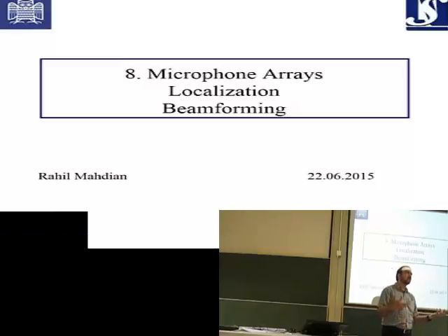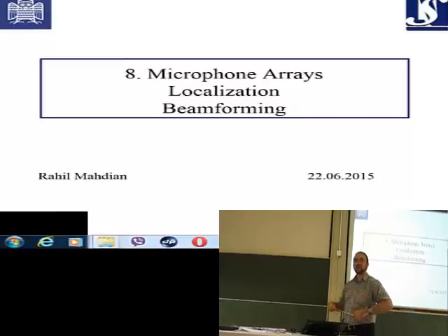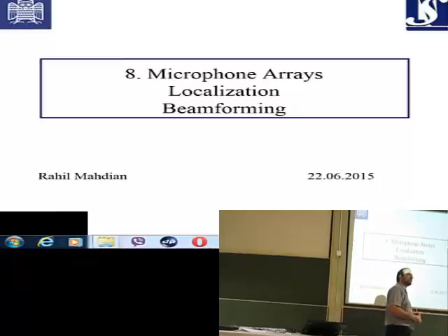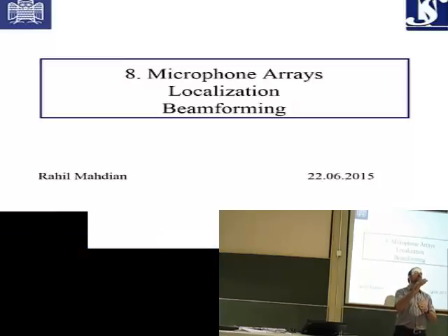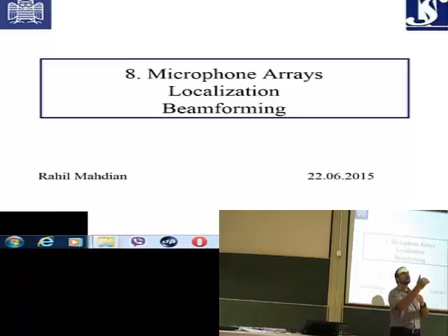In wavelets, we are not talking about frequencies in general, but about scales and resolutions, for the higher part, more resolution or less resolution. So the approximation of the signal corresponds to the lower frequencies, and the details of the signal correspond to the higher resolutions.